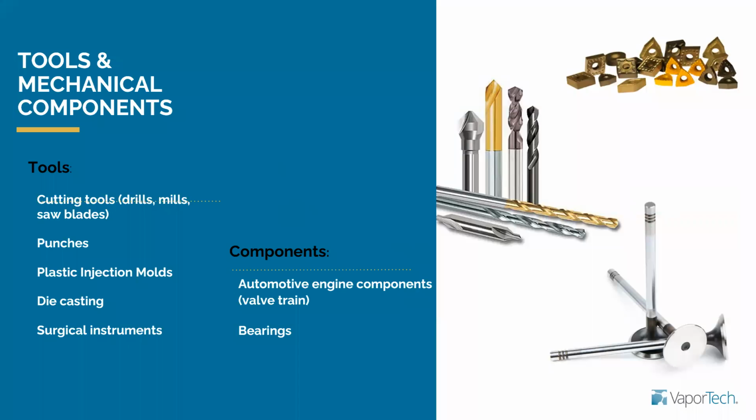Die casting has some interesting applications. It's similar to plastic injection molding, but a little more aggressive, because now you have, for instance, aluminum or zinc alloys in contact with your tools, and the tools have to be extremely resistant to the temperature and to reaction with those elements. With the high temperatures used in those processes to have molten forms of those metal alloys, you could have soldering of those alloys to the tool itself.